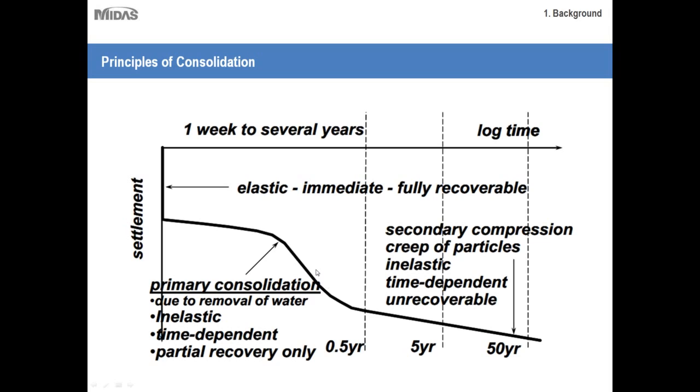So as you can see, once your project reaches secondary compression, the settlement really starts to level off here. So even though secondary compression is still something you need to account for, it's typically primary consolidation that's your main focus, just because it has the most amount of settlement in the shortest amount of time.